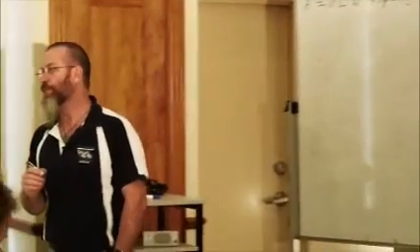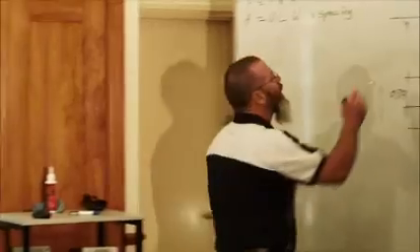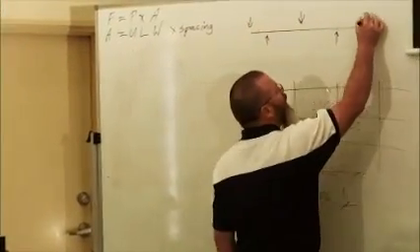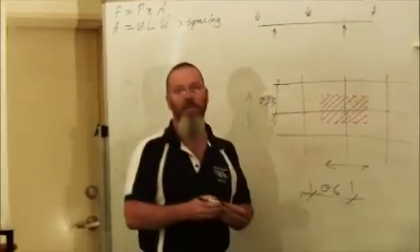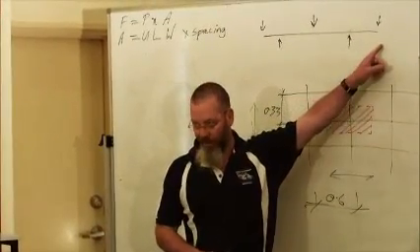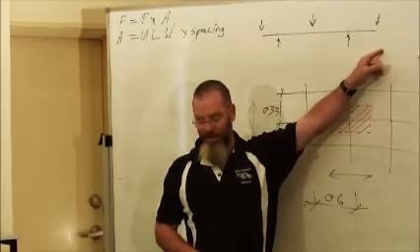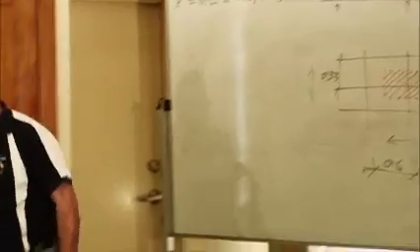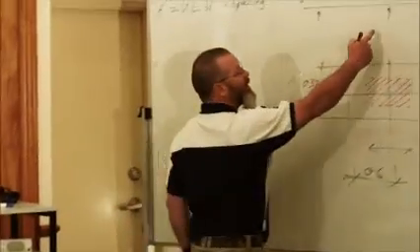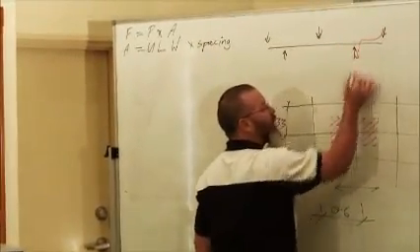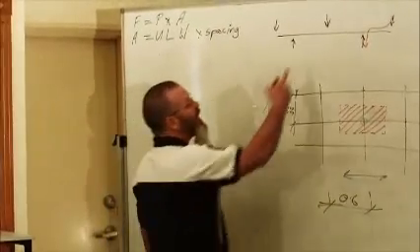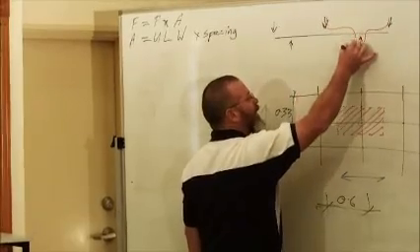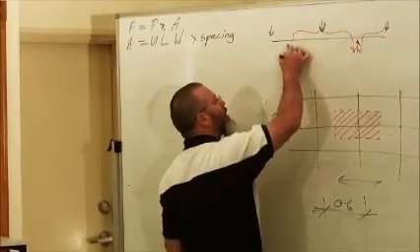There's the beam of a truss roof. That's it. I'm going to put a point load in the centre, and I'm going to put a point load here, and a point load here, just for the purpose of demonstration. If I was standing out on here, nailing the fascia on, which I'd never do, but just say I did, where would my load go? Think about the path of the load. Back down here, isn't it? Yeah? And then, if I was standing in the centre here, where would my load go? Half the load would go this way, and half the load would go this way.